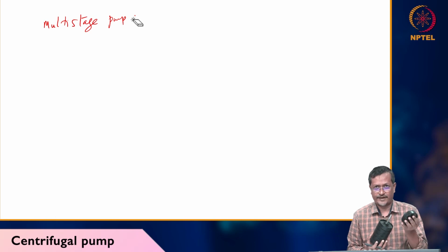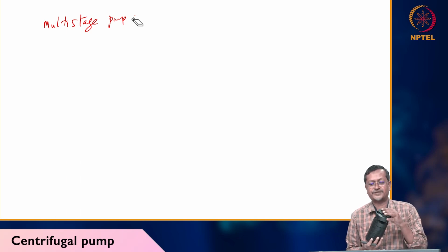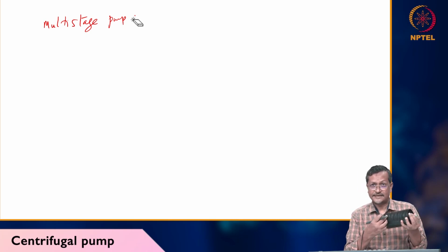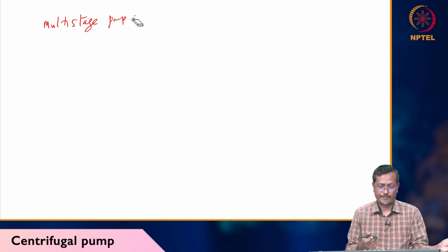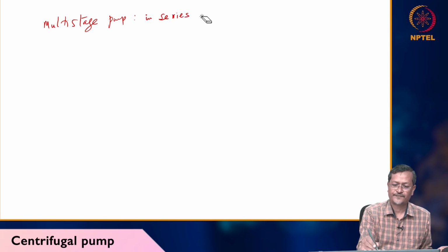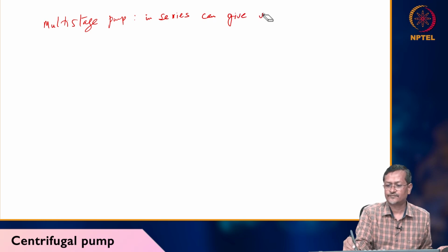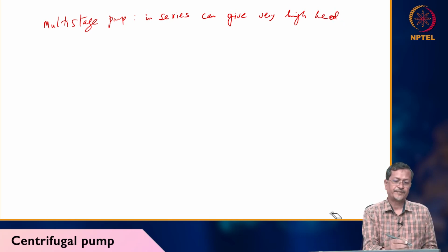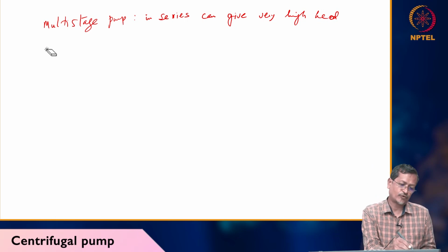For very high head, narrow applications, for example oil industry applications, as I already told, in that case this multi-stage centrifugal pump in series will be a very good application. Multi-stage in series can give very high head. Okay.